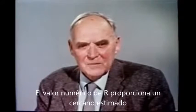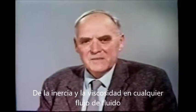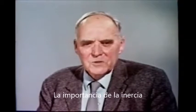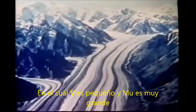The numerical value of R provides a rough estimate of the relative importance of inertia and viscosity in any fluid flow. When R is small, the importance of inertia is small compared with that of viscosity. Some examples are the flow produced by the movement of such small creatures as these bull sperms, for which L is very small, or glacier flow, for which V is small and mu is very large.